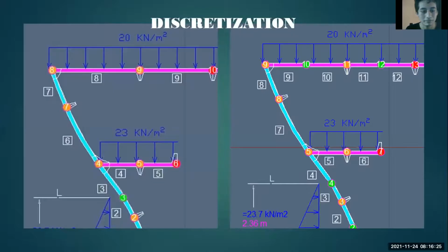Next, please. Well, the discretization was the part where we divide the frame into different elements according to our needs. First we establish where we already know we have simple supports and clamped points, clamped ends. And the only free joint we needed was here at the end of the seawater level, or the start of the seawater level, so we could employ easier math.